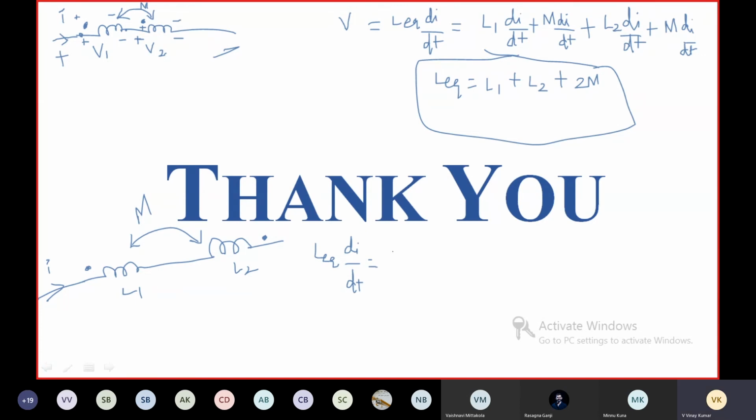what is the self-induced EMF in coil 1? L1 di by dt. What is the mutual induced EMF in coil 1? Let us find the polarity of the mutual induced EMF in coil 1. Here current is leaving the dot terminal, which means the mutual induced EMF in coil 1 will be negative at the dot terminal. Negative at the dot terminal means you are collecting negative voltage. Then you are going to get minus M di by dt.